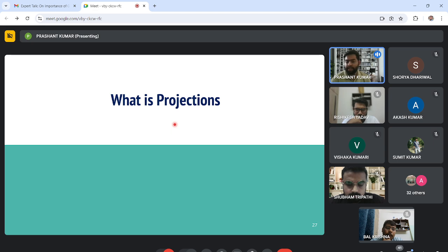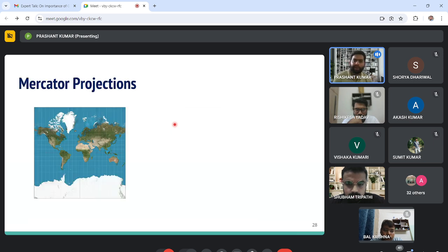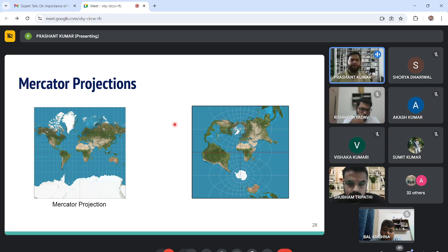Now, a major decision whenever a project starts is which projection system to go with. We may not have understood it that much in our earlier studies, but see what this selection can do. It's just two selections. On the left-hand side I have Mercator 3857, then I go with 4326. They transform the Mercator projection, and you see how my distances have changed, how the shape of the Earth has changed.